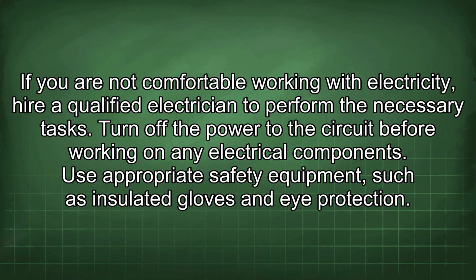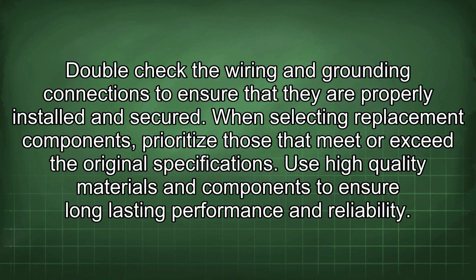If you are not comfortable working with electricity, hire a qualified electrician to perform the necessary tasks. Turn off the power to the circuit before working on any electrical components. Use appropriate safety equipment, such as insulated gloves and eye protection. Double-check the wiring and grounding connections to ensure that they are properly installed and secured.